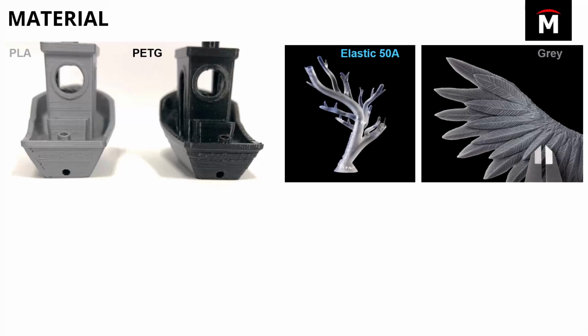Now if we look at the resin technology from Formlabs, they have a material called Elastic 50A, and as you imagine, it's a flexible material. And as such, it doesn't handle finer details quite as well, just given its elastic nature. Versus your standard gray material, which is incredibly accurate and is really good for prototyping, especially of super high detailed parts and doing things like injection molding where you don't want any layer lines. You need to capture all those really fine details when you actually go to mold and cast that part.